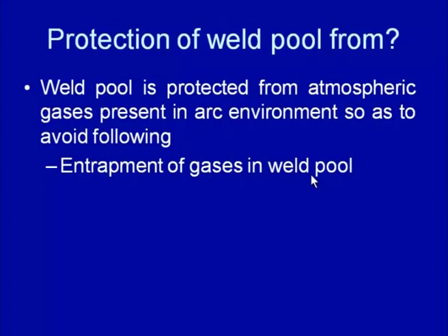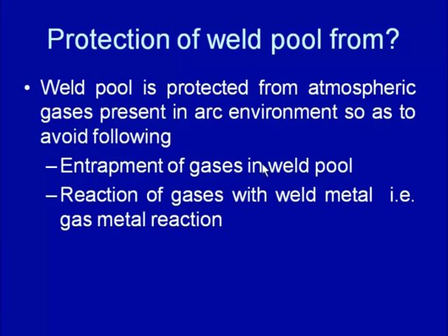It is important that the weld pool is protected from the atmospheric gases present in the arc environment, so as to avoid the entrapment of the gases in the weld pool. The atmospheric gases present in the arc environment, if they are not taken care of properly, then under the high solidification rate conditions of the weld pool, these gases can entrap and lead to gaseous defects in the form of blowholes and porosities.